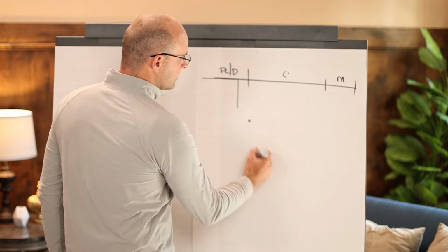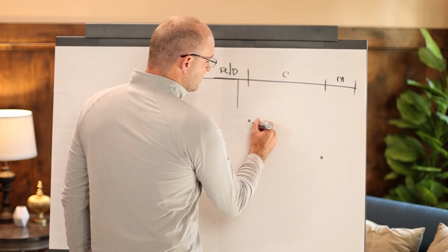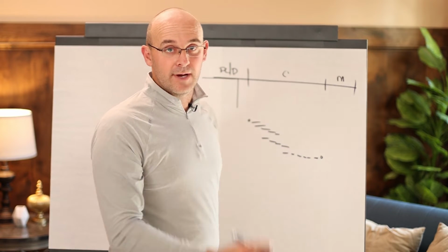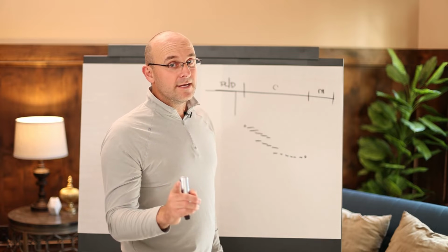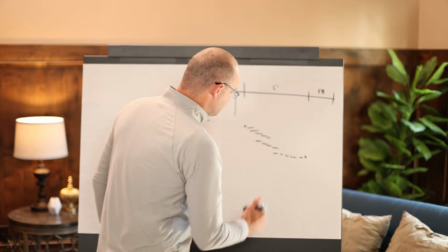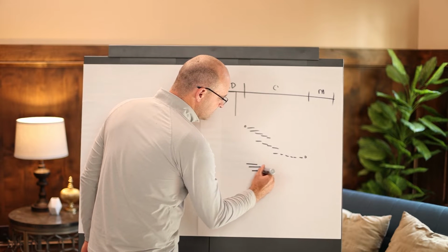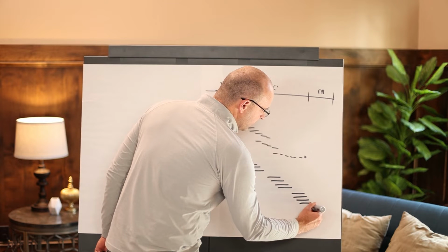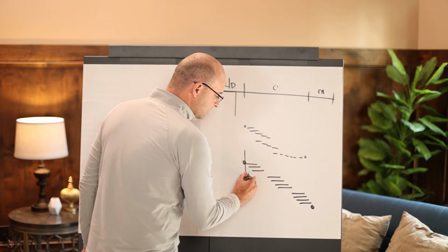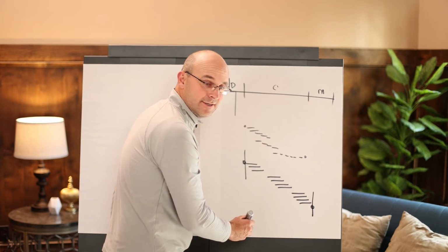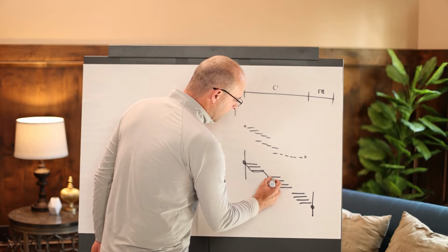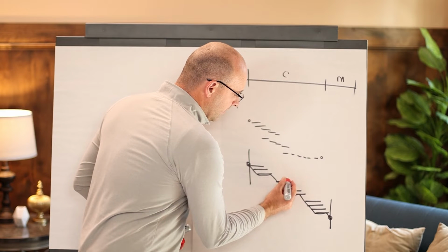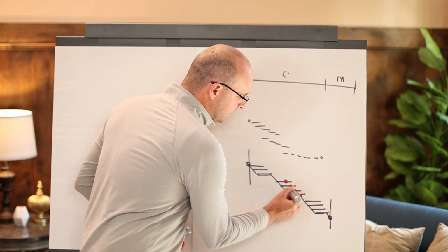If I'm looking at the schedule, the start date and the end date, and this is your schedule, let me do it in a CPM format, right? It has to be correct. And let me say this, it won't be unless you have trade flow. So what I like to do with these phases is to tact them out. So each phase will be a part of a tact plan, and I will know for a fact that my start date and my end date are correct because it shows the critical path going through phases, and wait for this, that have good trade flow. That means your trade can go from area to area to area in a flow.